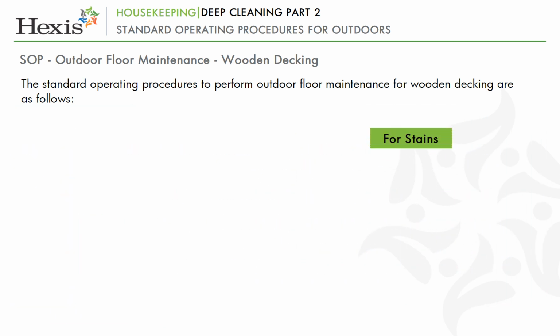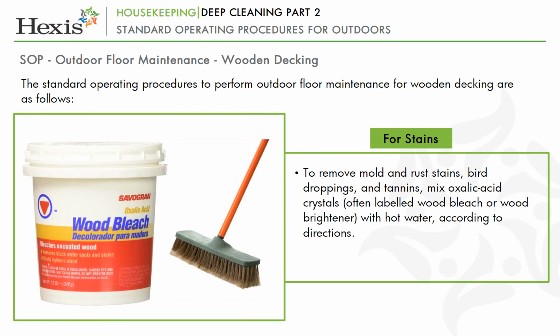For stains, to remove mold and rust stains, bird droppings and tannins, mix oxalic acid crystals, often labeled wood bleach or wood brightener, with hot water according to directions. Apply with a soft bristle brush or broom. After stains have faded, rinse well.